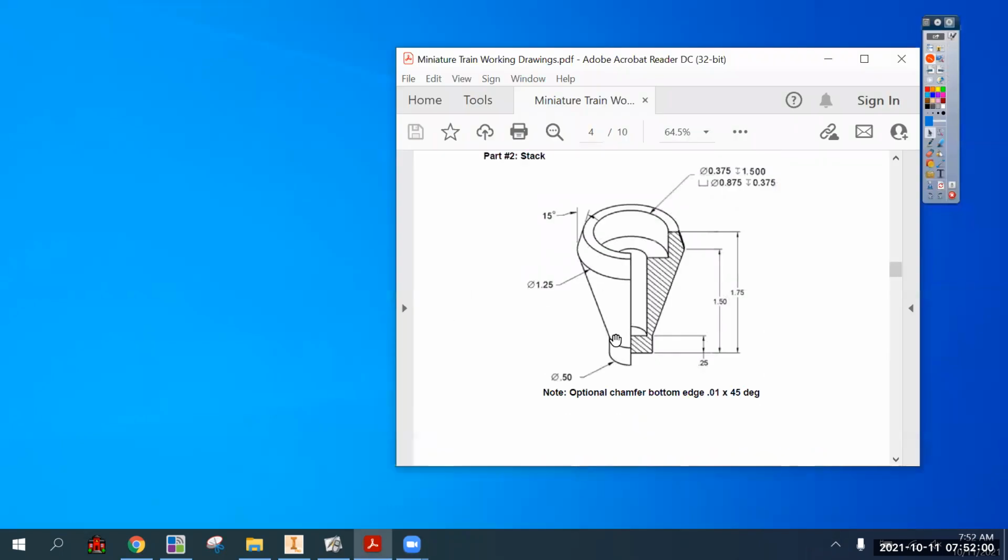All right, so we're going to start with Smokestack today, and there's two ways to do this. There's the way that the given dimensions are provided, and that's to do a revolve by drawing just the right half of this sketch and revolving it around the center axis.